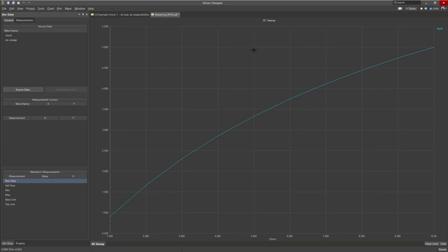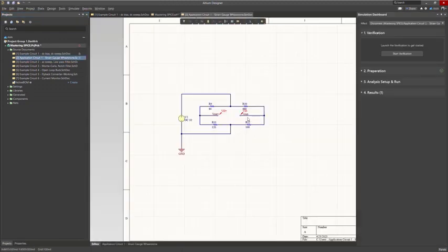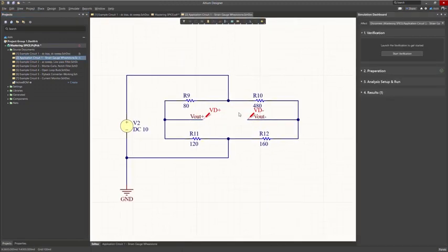So how is this useful to us? Well, let's take a look at this example over here, my strain gauge. Let's say I want to find what value of R12 is going to make it so there is no voltage difference between these 2 points. For that, I'm going to do a DC sweep of R12 just like we did for R7. So let's again do this verification.